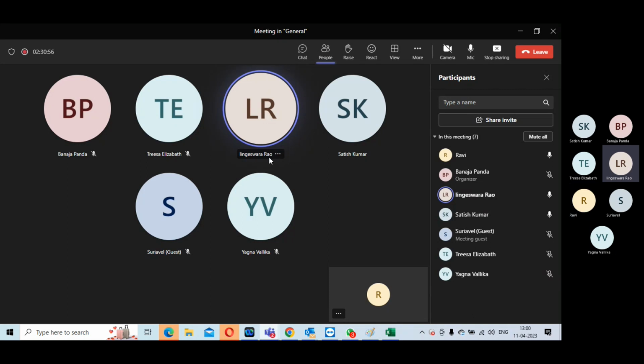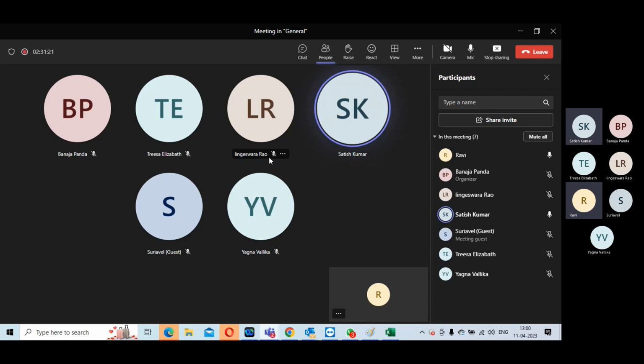Before you exit your floor plan, your floor plan DRC should be clean. So enable fill and run your DRC checker. You should not have any shorts, power shorts should not be there. Base layer DRC should be clean. Filler base DRC should be clean.